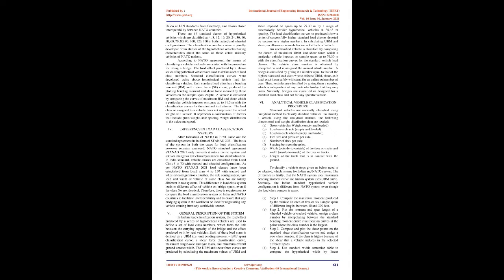4. Difference in load classification systems. After formation of NATO in 1970, came out the standard agreement in the form of STANAG 2021. The basis of the system in both the cases for load classification however remains unaltered. NATO Standard Agreement STANAG 2021 only converts it into a metric system and adds or changes a few clauses/parameters for standardization. In India Standard, vehicle classes are classified from load class 3 to 70 with tracked and wheeled configurations. As per NATO STANAG 2021, load classes have been established from load class 4 to 150 with tracked and wheeled configurations.